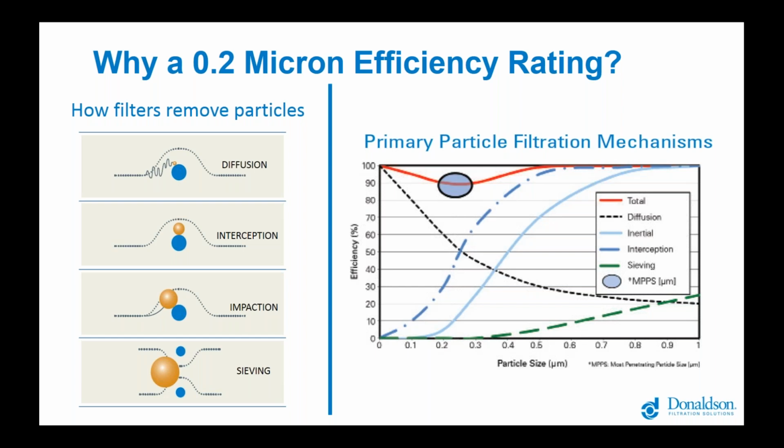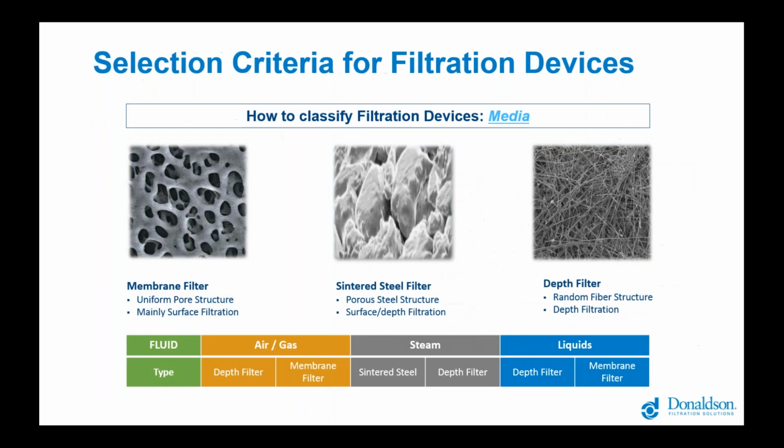So now that you know a bit about the contaminants that are captured, let's look at some of the filter medias that are used. So the most common formulations of medias used in food and beverage applications, they all have pros and cons, and the options exist so that the best choice can be made after understanding design intent and application details. On the left, we have a membrane filter. It looks a bit like Swiss cheese from the top, but that actual internal structure is quite complex. You can actually see the pores, and you can imagine a bacteria, for example, being captured because it can't fit through that pore, similar to how a chain link fence would stop a baseball.